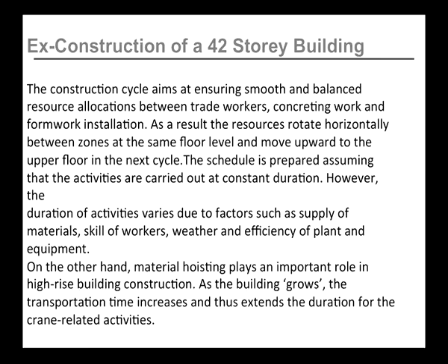The construction cycle aims at ensuring smooth and balanced resource allocation between the trade workers, concreting work and the formwork installation. As a result, the resources rotate horizontally between zone 1 to zone 2 at the same level and move upward to the upper floor in the next construction cycle.